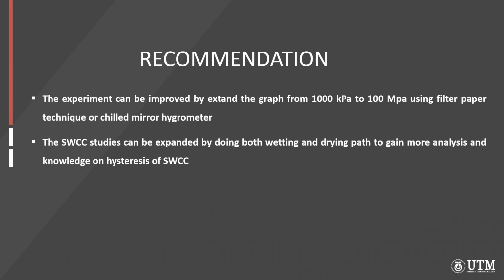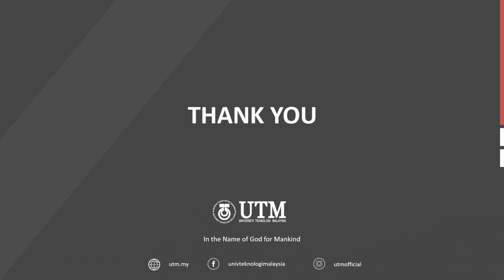The recommendations of this research are: first, the experiment can be improved by extending the graph from 1000 kPa to 100 MPa using the filter paper technique or chilled mirror hygrometer. Secondly, the SWCC studies can be expanded by doing both wetting and drying paths to gain more analysis and knowledge on hysteresis of SWCC. That's all from me.